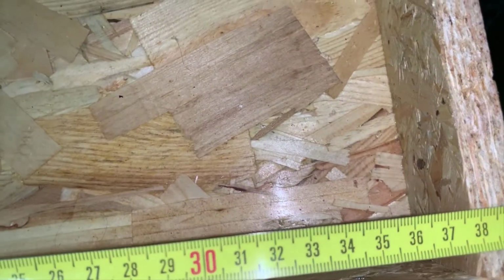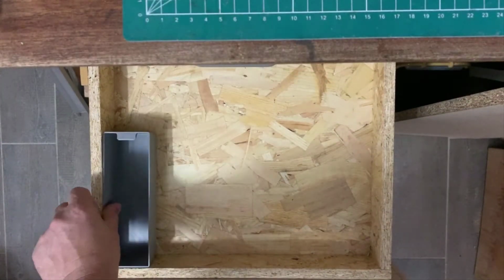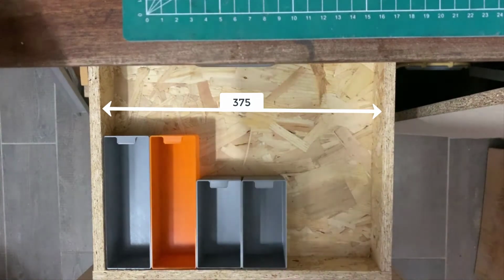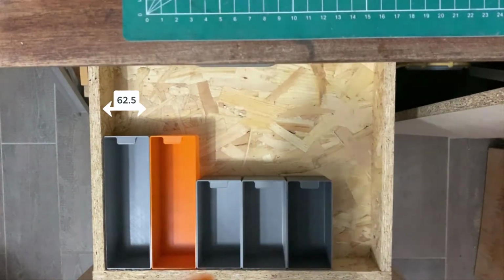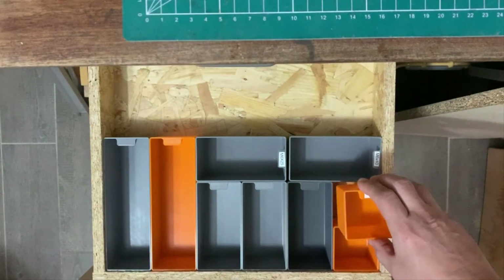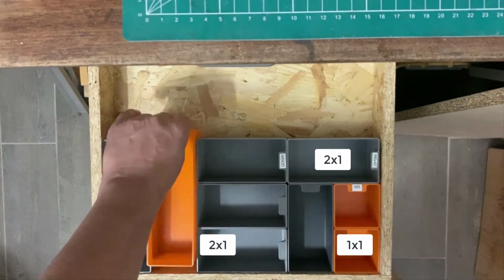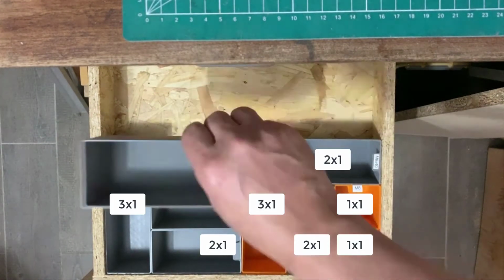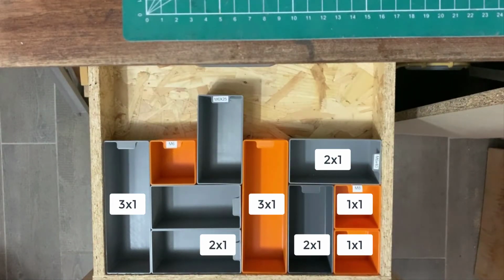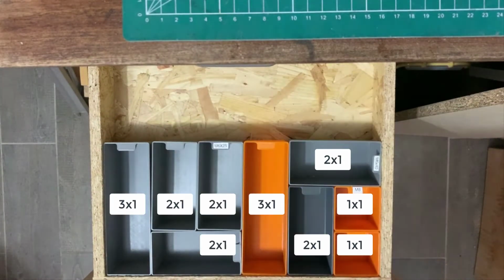We take the width of the drawer, here 375 mm, and 6 boxes fit in this direction. The value of the unit will be 375 divided by 6. Unit is 62.5 mm for this drawer. Now, all boxes will have dimensions that are multiples of this unit and they will fit together first time. We will thus forget 62.5 mm for boxes that are now simple 1 by 1, 2 by 1, 3 by 2, and so on. Now, let's start modeling.